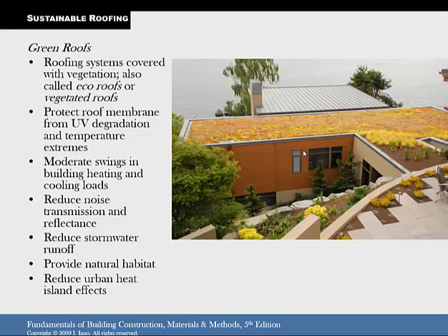Here's a garden roof. Of course, with this, it's very important that you detail it correctly, because there's massive potential for leaks in this system. But again, if it's done right, it can be very good for improving the environment, and basically this replaces the vegetation you removed below when you built your structure. So you're not taking away from the environmental air quality.